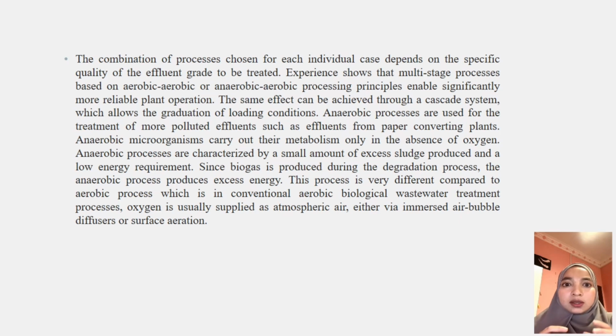Anaerobic processes are characterized by a small amount of excess sludge produced and a low energy requirement. This is very different compared to the aerobic process. In conventional aerobic biological wastewater treatment processes, oxygen is usually supplied as atmospheric air, either via immersed air bubble diffuser or surface aeration.